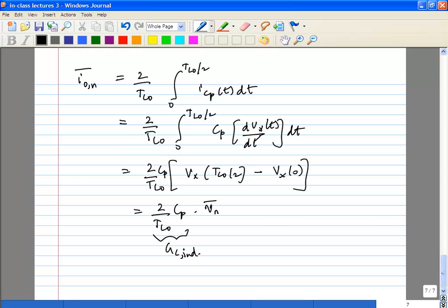So this is the conversion gain for the noise for the indirect path. What do we see? Of course, the conversion gain increases with the frequency. So definitely, if you have a higher frequency LO, the noise through the indirect path will tend to be higher. Usually, it will be much lower than the other noise, but it's something to keep in mind, because it depends on the parasitic capacitance as well as your FLO.